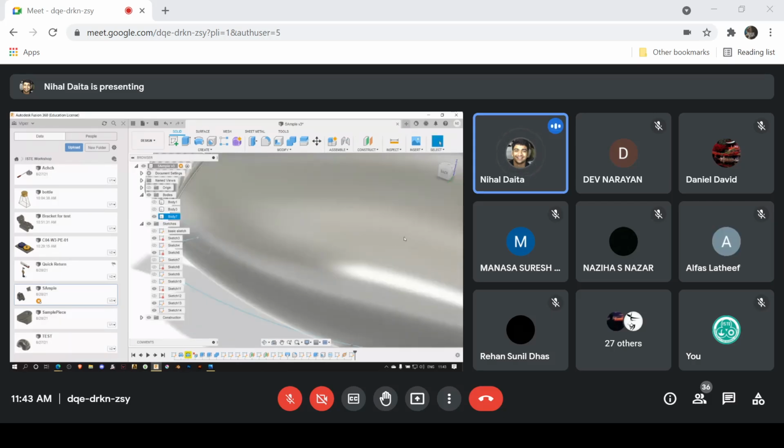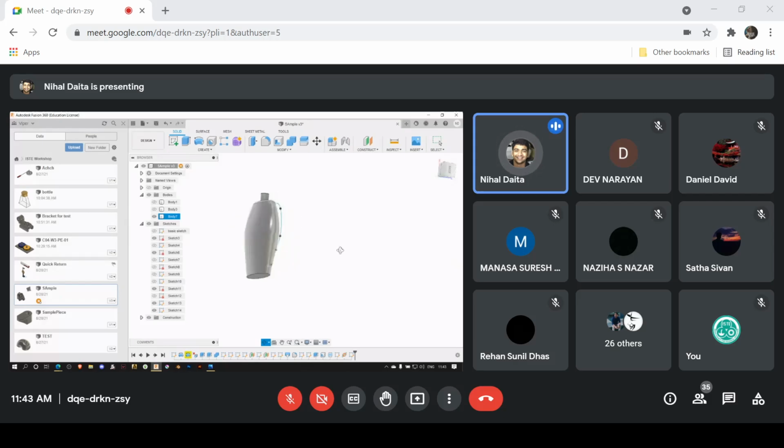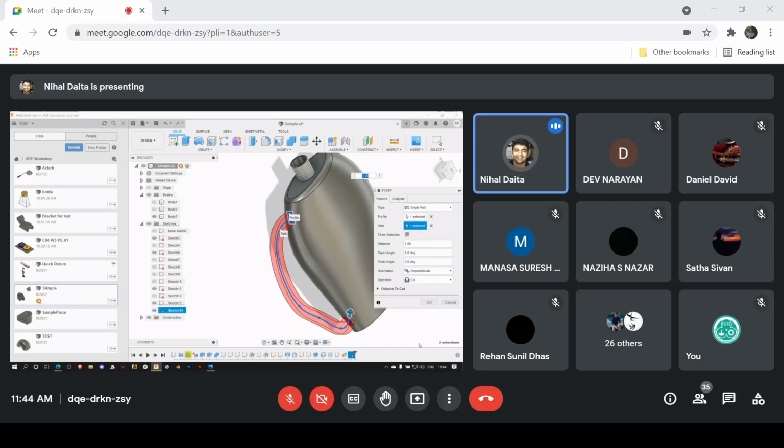Okay, that doesn't work. Fine. When you work on it as well, you'll have a lot of these rotations and orbital movements, right? So bear with me. I want to use this rectangle and drag it along. It's to be noted that I think both of them should be separate sketches and not the same sketch. I think that was a problem. I'm not exactly sure, but it's better practice this way. So I can select sweep, right? You choose the object to sweep, and you click the path along which it should be swept.